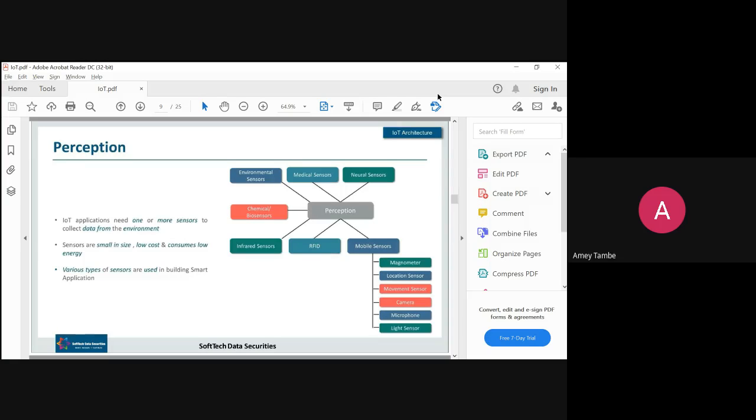Then it checks the weight with the weight sensor, and then it goes to the second station for tightening the lid. Again, there are IR sensors and visual sensors which examine the bottle lid, whether that bottle is already packed with the lid or not. If the bottle is not packed with the lid, then the lid is placed on it, and another machine tightens it up. Then it is checked for quantity and quality using visual inspection sensors. These sensors are responsible for ensuring the right amount of product. If the bottle shape is not proper, or the bottle is not properly packed, or the product is not properly filled, maybe it is overflowing or not at the mark, then that bottle is automatically rejected.